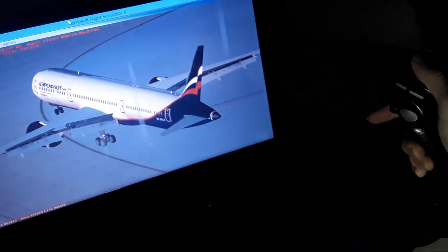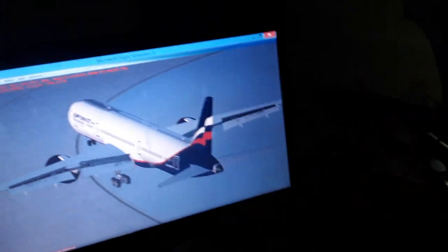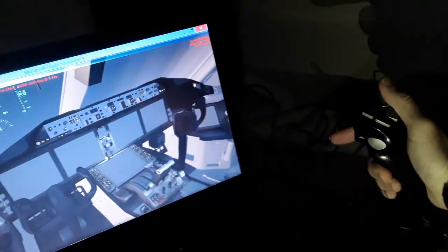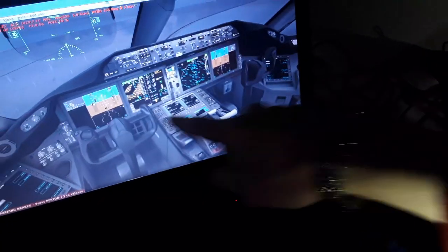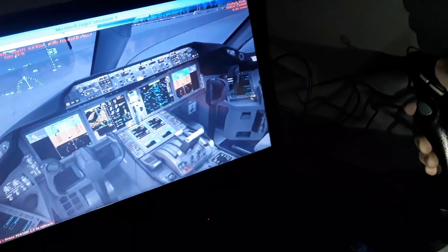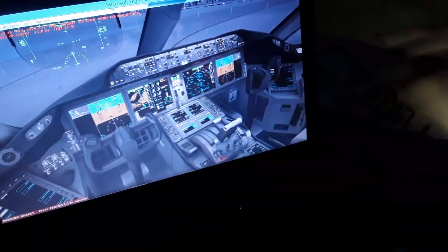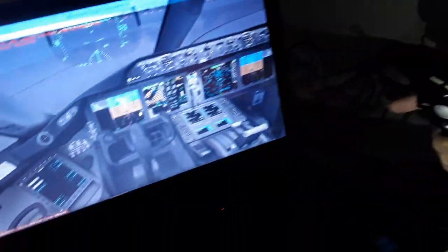Or 18 knots in takeoff. So you see again the rudder pedals over here make left and right turns. The nose wheel steering is 76 degrees up to 45 knots, then 7.6 degrees, then to 80 knots decreases to 0. You have only the rudder. Rudder is aerodynamically effective above 45 knots. Also you have the nozzles, the tiller over here. So this is the yawing control.